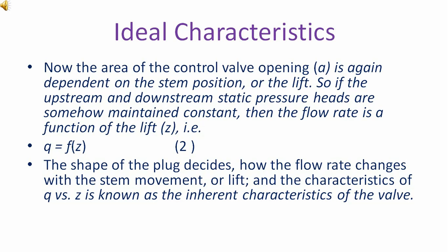The shape of the plug decides how the flow rate changes with the stem movement or lift, and the characteristic of Q versus Z is known as the inherent characteristics of the valve.